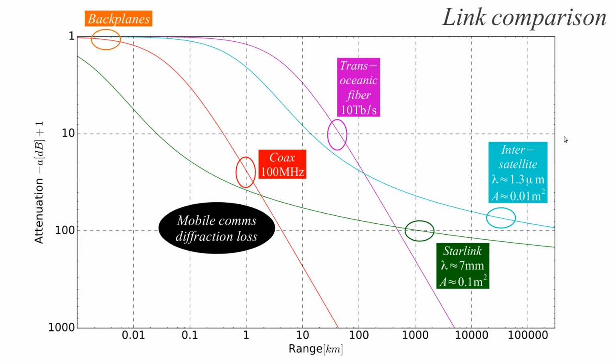For very long distance, we may have radio communication. The best example today is the Starlink space internet. The distance between the user and the satellite may get, with the satellite low on the sky, satellites are 500 kilometers high here, but you may get to 1000 kilometers or even 2000 kilometers when the satellite is low on the sky, at millimeter waves with directional antennas on both sides of the links, electronically steerable directional antennas for Starlink.